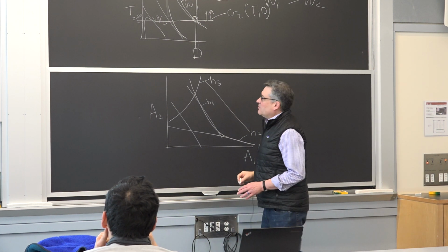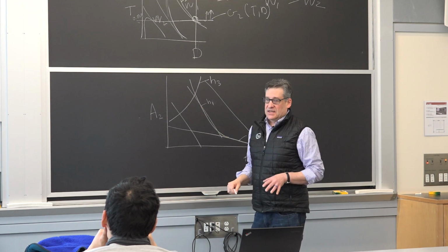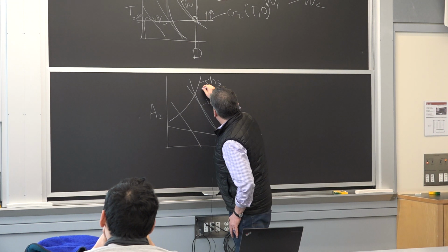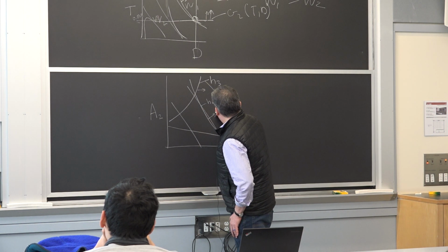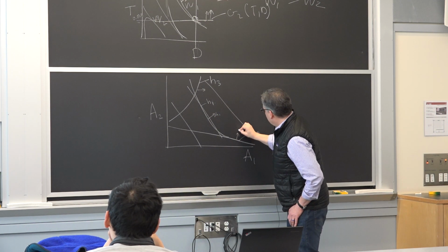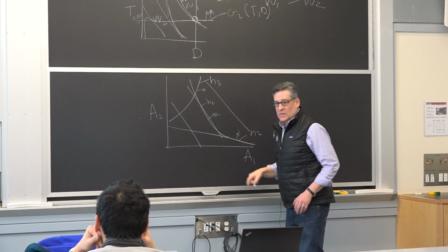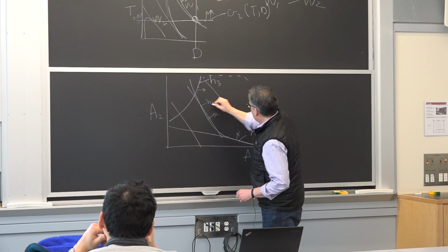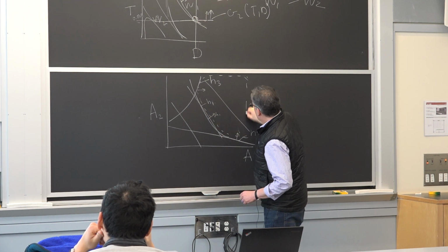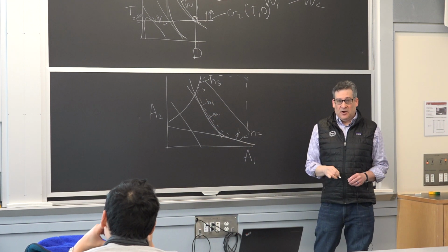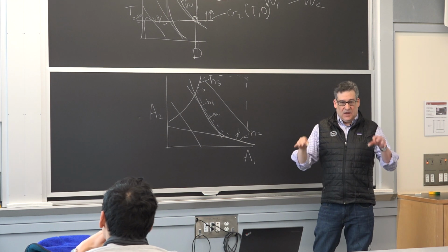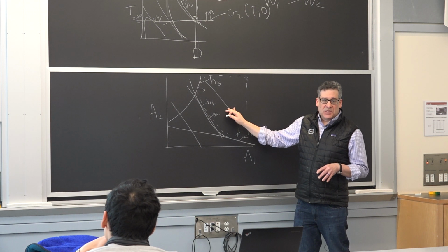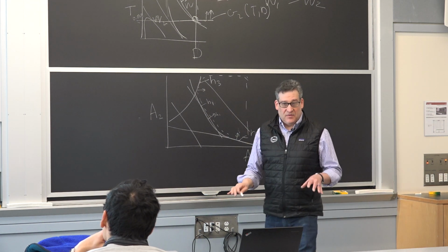Okay. And based on the way I've written the constraints, we've designed these functions, H1 through H3. We want to be this side of H3, this side of H1, and then this side of H2. Right? So that means the feasible region is this area here. This is the feasible region. These are the areas where we could design these things. We could pick an A1, an A2, and an A3, and that would not violate our constraints. We would not be in a situation where we're above the stress limit of those rods.